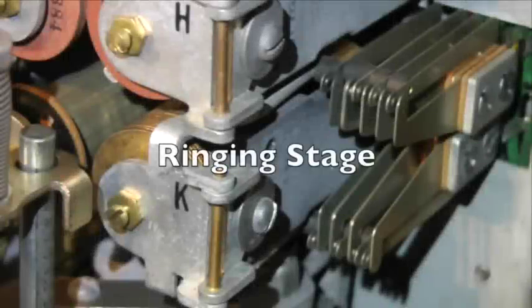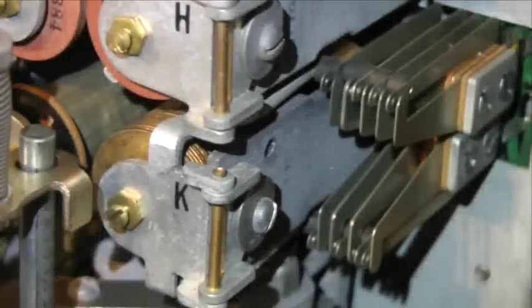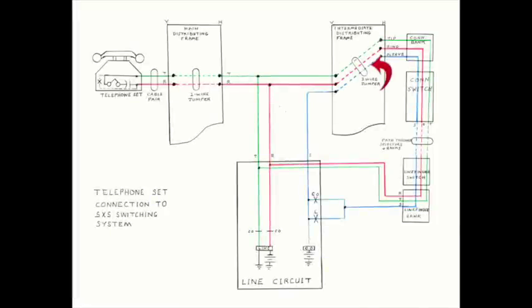If the called line is idle, the sleeve lead will not be grounded and the G relay will not operate. Instead, when the slow release E relay releases, one side of the primary winding of the K relay will be connected to the sleeve wiper, and the other side of the winding will be connected to ground. The called station's sleeve terminal is connected through the IDF jumper to the called station's line circuit. In particular, it is connected to one side of the cutoff relay winding. The other side of the CO relay winding is connected to the negative 48-volt battery. This completes an operating path that operates both the CO relay in the line circuit and the K relay in the connector.